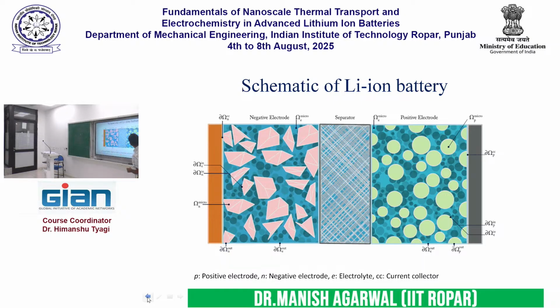So these electrode particles are there, right? If you see this boundary, at this reaction, lithium is decomposing into lithium plus and an electron. Everything is happening at the boundary between the electrode particle and the electrolyte. They only talk to each other at the boundary. This reaction is the main driver of the current. If this reaction doesn't happen, the current is not going to get generated in the lithium ion battery.